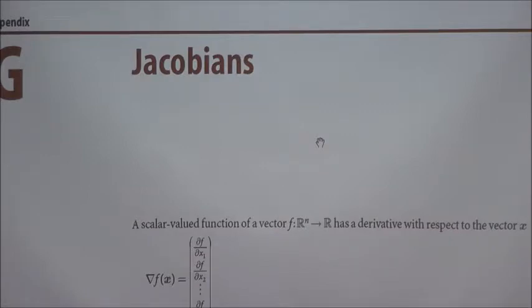You need to find a trajectory for those velocities to make the robot go from A to B, and along the way avoid some obstacles. Which means if you use MATLAB or Simulink, you need to add some of your own if-then rules logic, in either fuzzy or non-fuzzy fashion, to avoid obstacles.